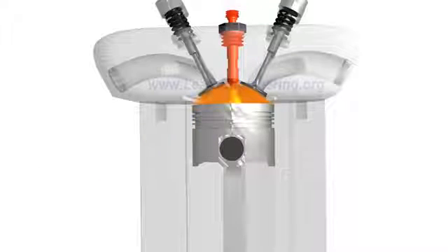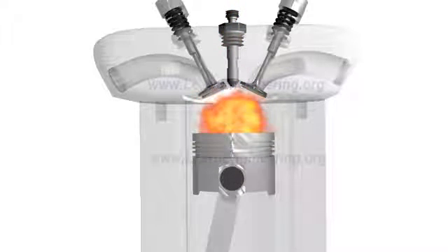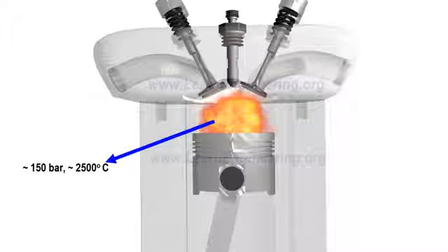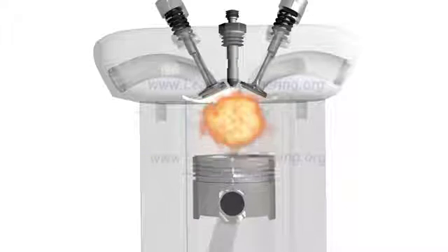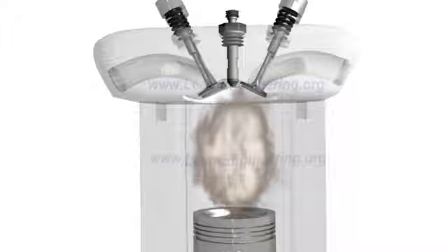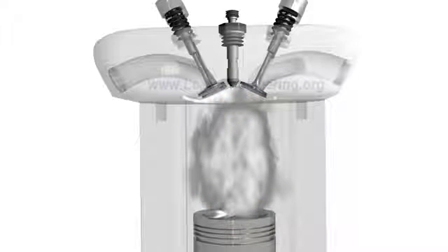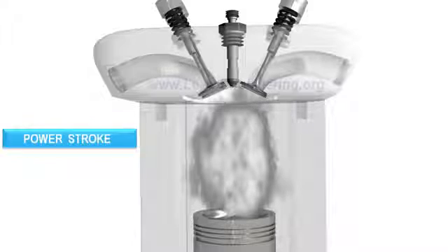An atomized form of diesel is injected into this compressed air. The fuel gets evaporated and undergoes an uncontrolled spontaneous explosion. As a result, the pressure and temperature rise to high-level values. The high-energy fluid pushes the piston downwards. The hot air does work on the piston, and energy in the fluid is converted to the mechanical energy of the piston. This is the only stroke where the piston absorbs power from the fluid.